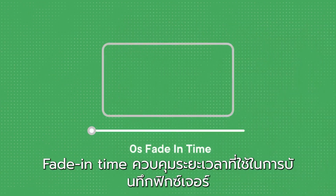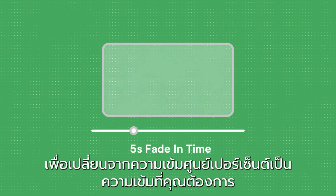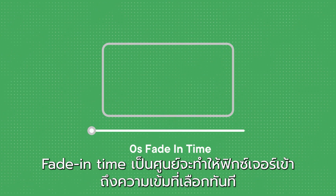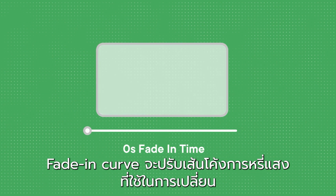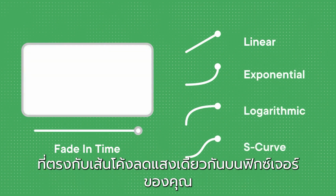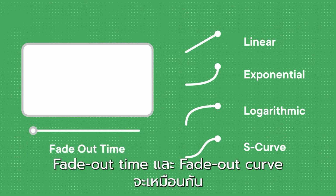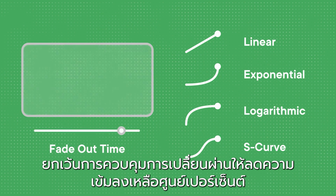The fade-in time controls the duration of the time it takes for the node of a fixture to transition from 0% intensity to your desired intensity. A fade-in time of 0 will cause the fixture to instantly reach the selected intensity. The fading curve will adjust the dimming curve used to transition. You can choose from linear, exponential, logarithmic, or S-curve, matching the same dimming curves on your light fixture. The fade-out time and fade-out curve are the same, except they control the transition down to 0% intensity.